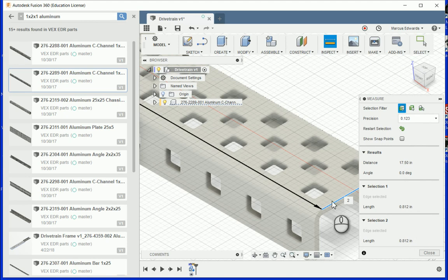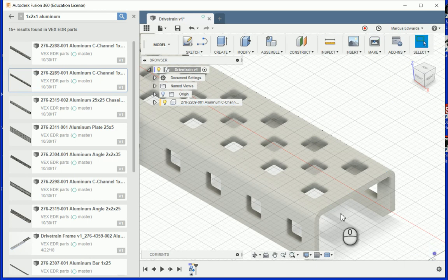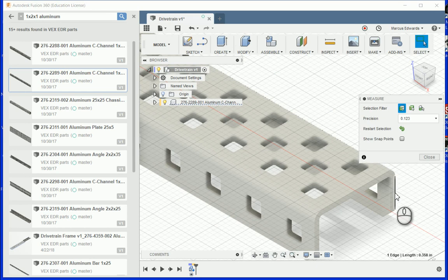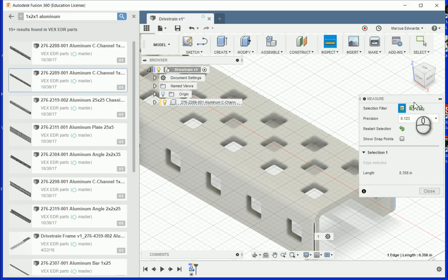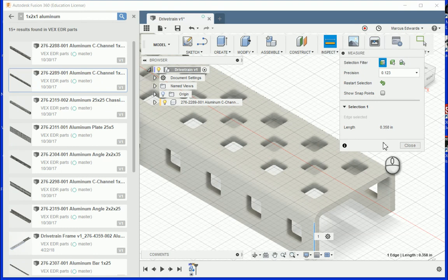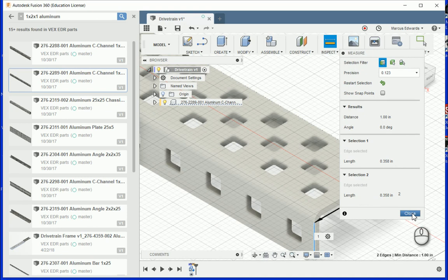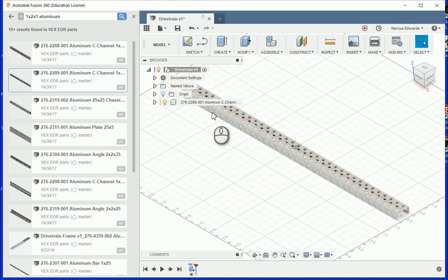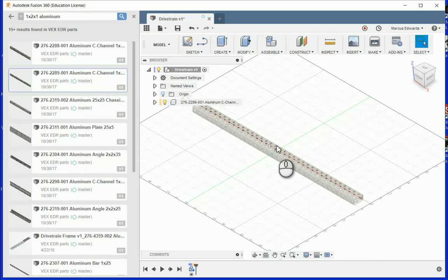And anyway, it's also telling us the distance from this bend across, and that wouldn't give you the total distance because we'd actually have to come from this plane and this plane. So when we press I, we can do this again, here to here, and it'll actually give you that length located right there. Two selections, it's exactly 1 inch, in theory. So here we go. There's a couple different things. We could ground this particular component, and this box is going to tell us a couple things. It's going to tell us if it is a body, a component, or an assembly.